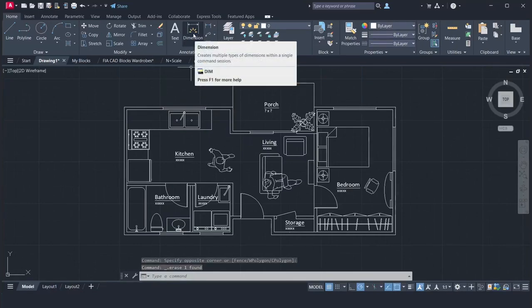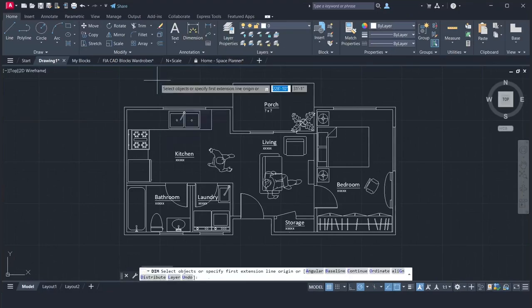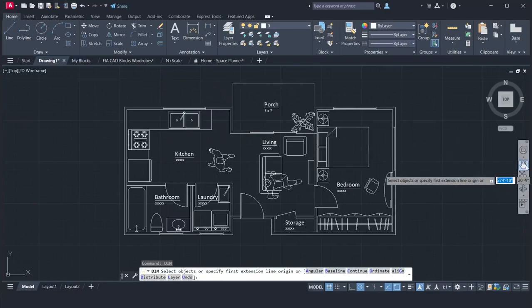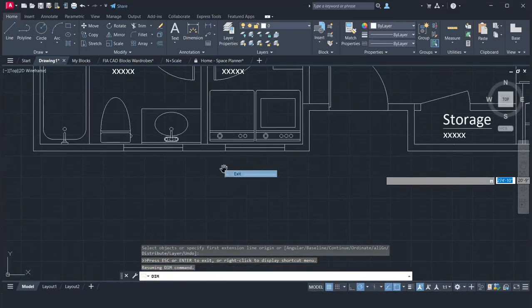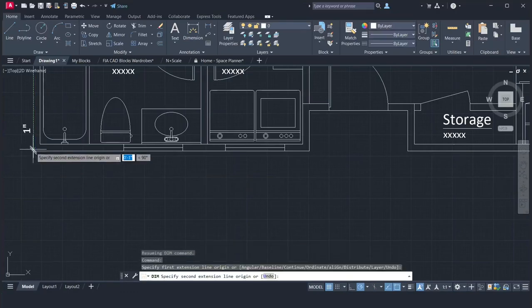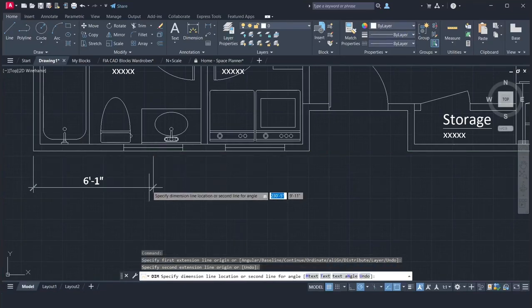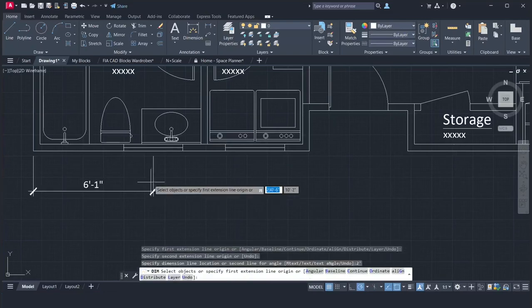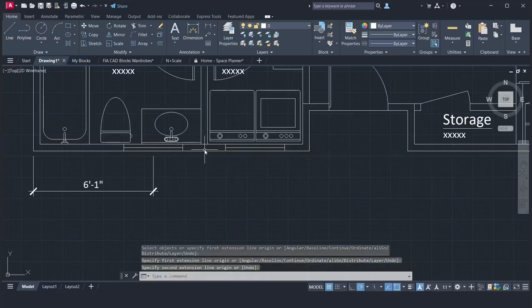Click this button to add dimensions. Alt-Tab, DIM, Enter. If we made windows, doors, or interior walls, we should use the midpoint of them. This way, I like to go with 2 feet. No midpoint here. Press the Esc key to access the dimension command.